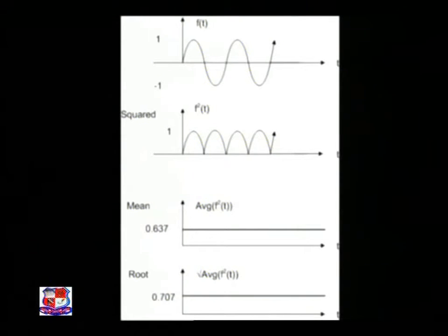But what if not all of these peaks are the same size? How do you account for peak variation? You account for it in the same way you would normally. You take a mean value. So, let's go through the steps. We want only positive values for our current, so we square everything. This makes it too big. We want to account for any variation in the magnitudes of these peaks, so we take an arithmetic mean. We want to bring these results back down to the size they were originally, so we square root them. This is how we do a root mean square.